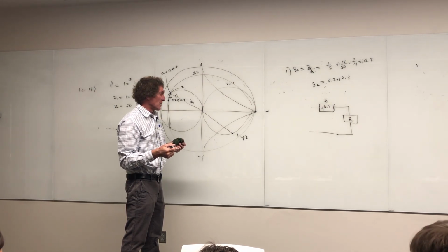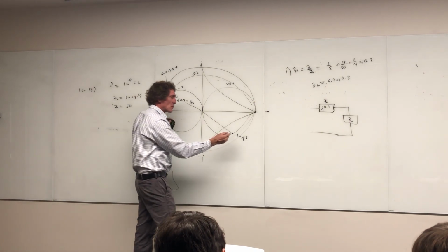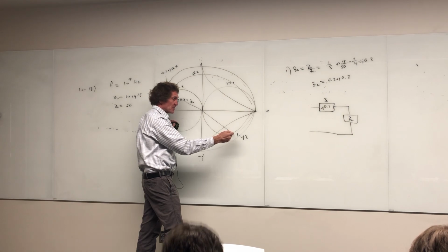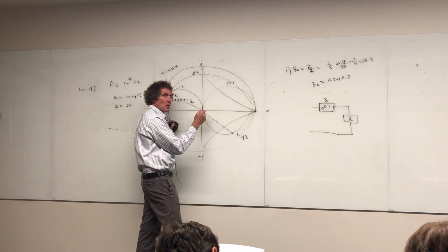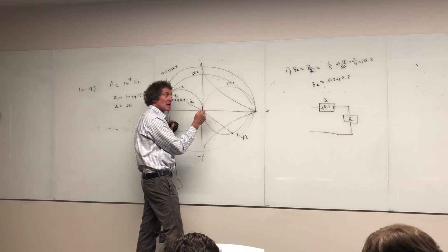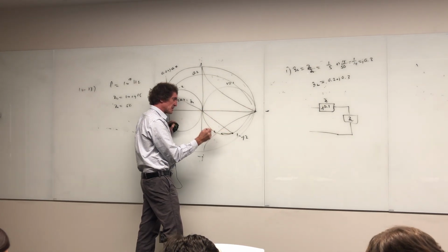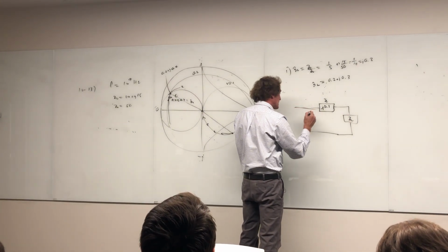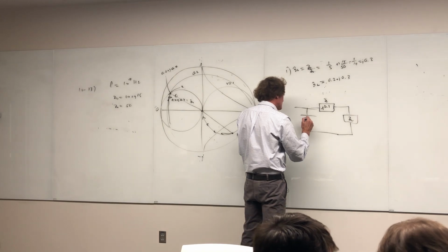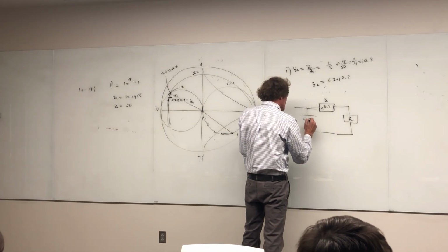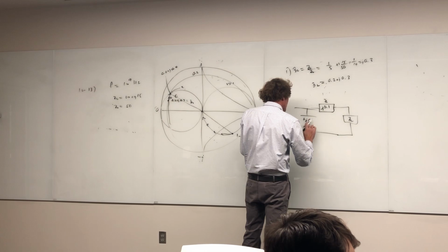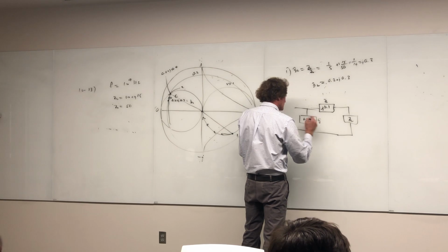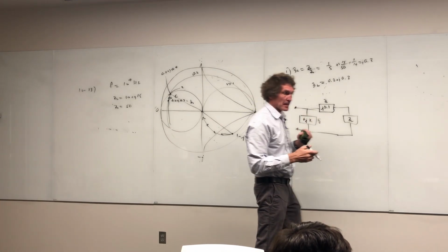All right. Now, we're here, and we're in the admittance domain, right? We want to add something to get to this point. What has positive j admittance? Capacitor for sure, right? So then we're going to go this route, and we're going to get right to this point by adding j, and that's going to be a parallel element, right? It's going to be plus j0.2. That's admittance.